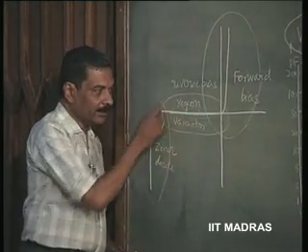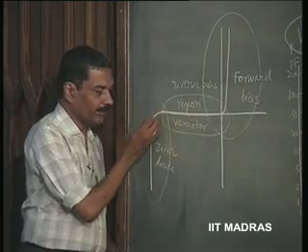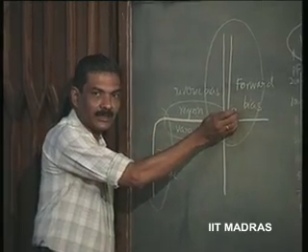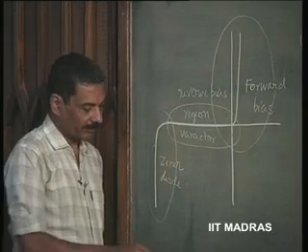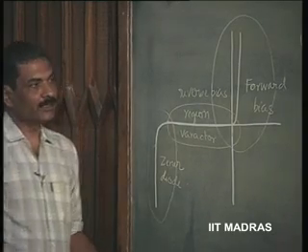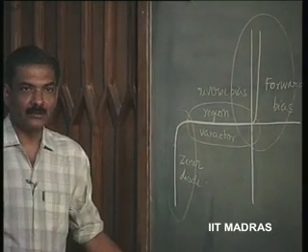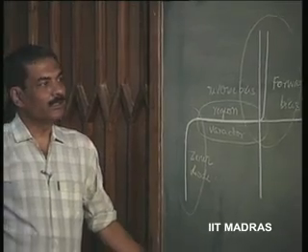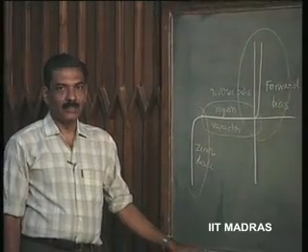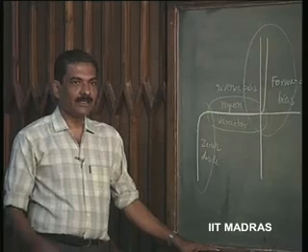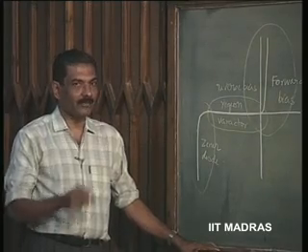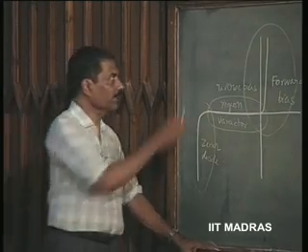In this region where it is neither breaking down nor going to the forward region, when it is biased properly, it can be used as a capacitor. Where do you use this variable capacitor or varactor diode? Whenever we want an LC oscillator, we will discuss this later, whose frequency of oscillation has to be varied by varying a voltage,